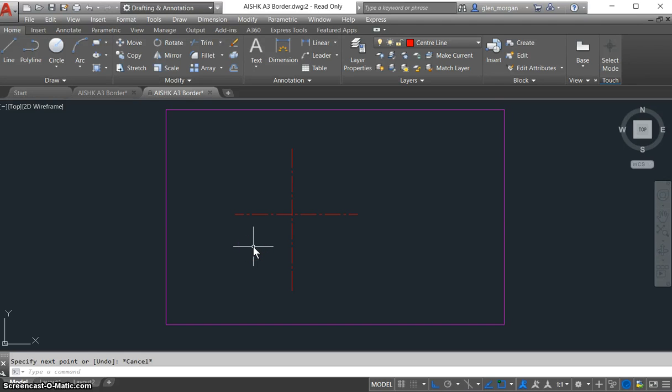In this video we'll continue drawing some different types of lines and some circles, but we'll also use the fundamental tools of AutoCAD: the trim tool and the offset tool, which is this one here, and the extend tool, which is opposite to trim, the extend tool up here.